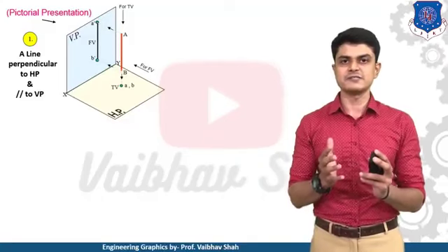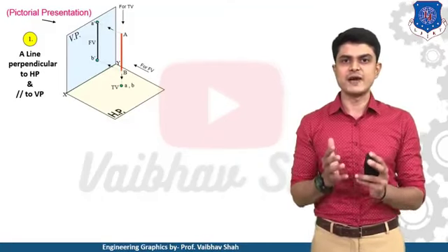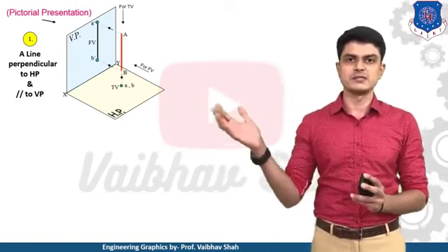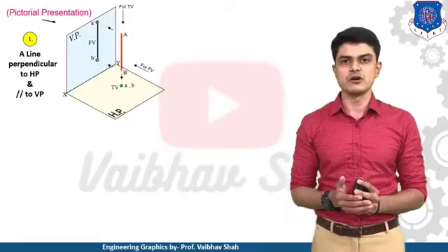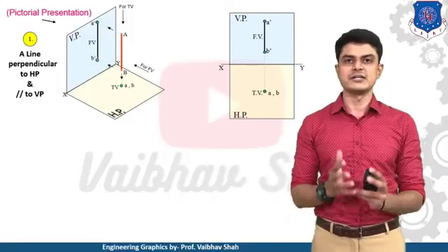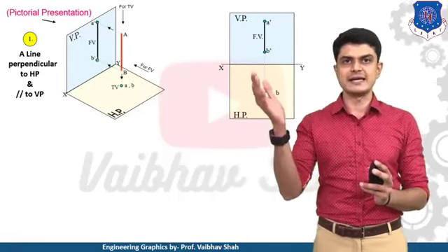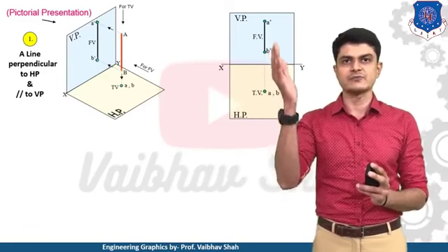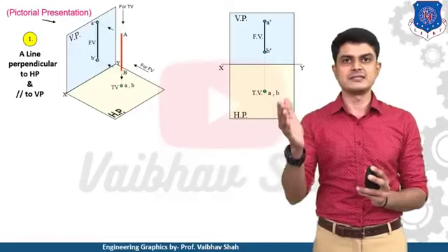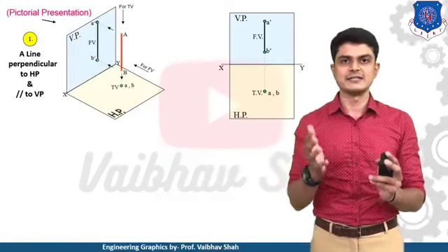Now this is a 3D representation of your object. This is the orthographic projection of lines, but it is very difficult to draw in actual practice in examinations. So we will try to convert these 3-dimensional orthographic views of the line into 2-dimensional clearly understandable views. In examination, it is required to draw this kind of view in which you first draw your XY line, and you draw this vertical line above the XY line and its top view just below this line in vertical fashion like this. In examination, you are required to draw this diagram and it carries marks.